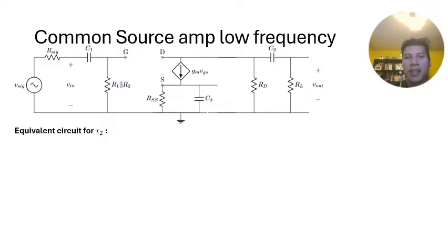associated resistance. To look at the second capacitor, we remove this capacitor because we're going to be looking into R Thevenin 2 here, and we're going to short out all other capacitors. And again, remember when we're looking for our Thevenin, we always short out any external source. So let's draw our circuit.